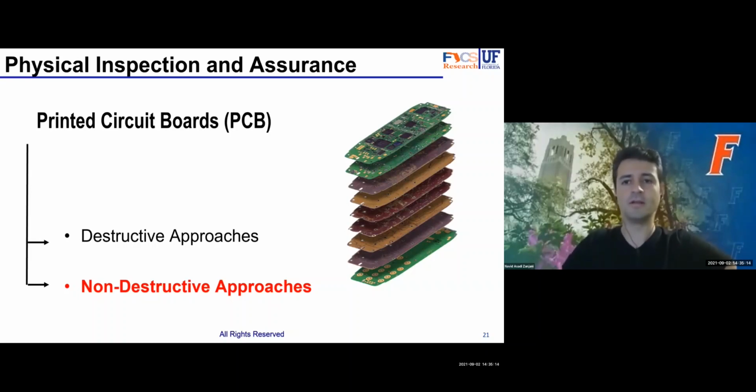inductors, and a lot of high Z material, X-ray gets very much attenuated. So when the X-ray is attenuated, because of the reconstruction process, we end up getting a lot of noise, okay? And that noise is brutal in evaluating and authenticating the board. Sometimes a lot of traces may be covered by this noise. And if that little trace or the via is the one that potentially is modified maliciously, no way to extract it.